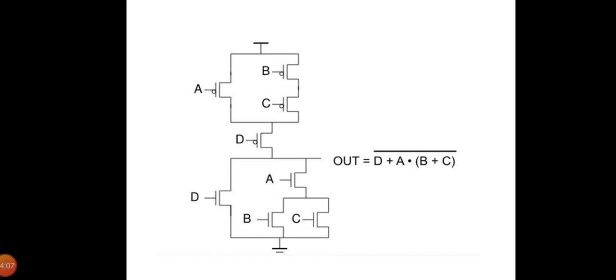Now let us consider an example. The output capacitance is initially charged to VDD. Two possible discharge scenarios are seen. One is an NMOS device pulling the output all the way down to ground, while the PMOS lowers the output no further than VTP. The PMOS turns off at that point and stops contributing discharge current. NMOS transistors are thus the preferred devices in the pull-down network.